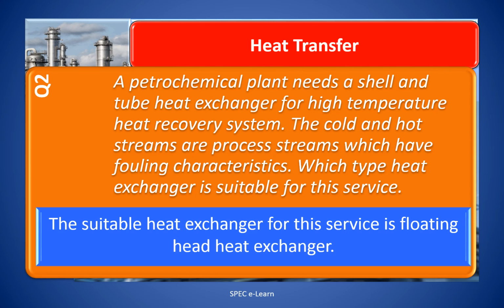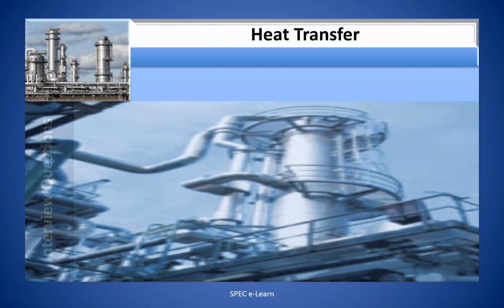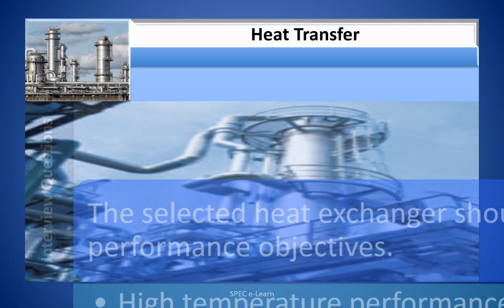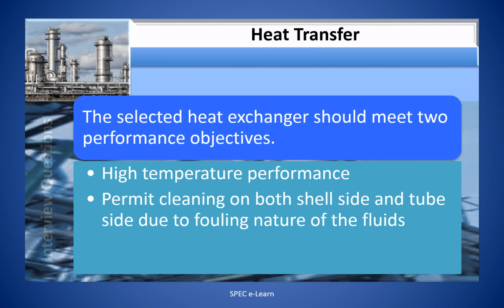The time is up. The answer. The suitable heat exchanger for this service is floating head heat exchanger. The selected heat exchanger should meet two performance objectives. 1. High temperature performance. 2. It should permit cleaning on both shell side and tube side due to the fouling nature of the fluids.